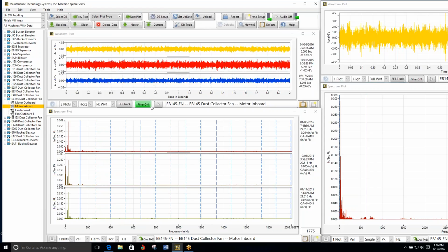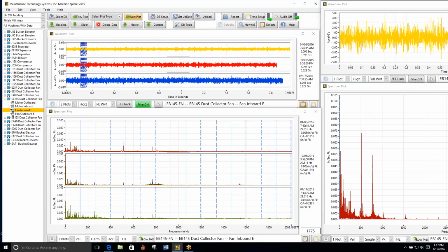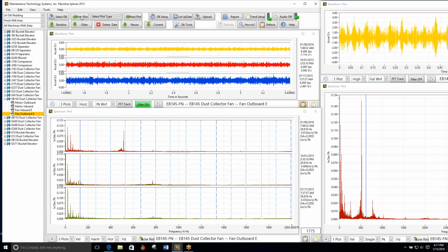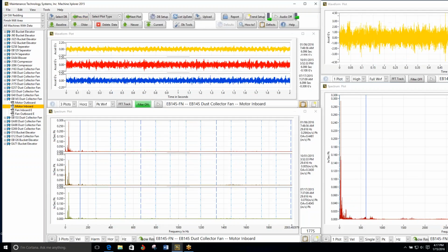Well, that's just on the edge. But what do you do with a motor that's got a higher vibration other than to watch the thing? You're not going to go balance the motor. Probably just need to clean some dirt off the pulley. I would also tell them to check the belt pulleys for run out and alignment, because you've got both frequencies in both machines. Yeah. More so on the motor though. And check for a soft foot on the motor too. Or it can respond more to that pulley run out.